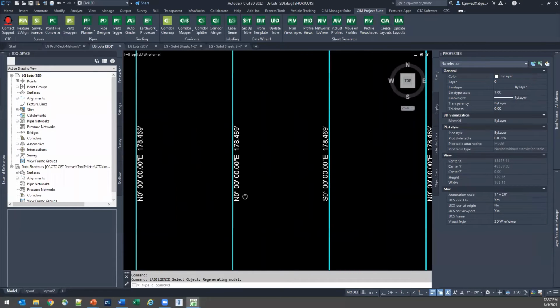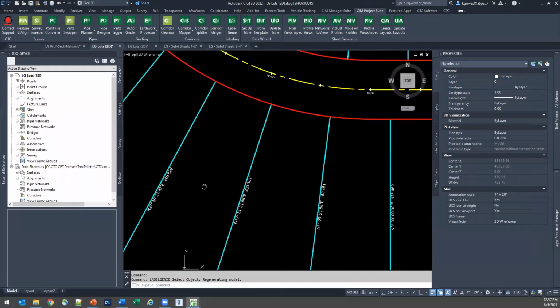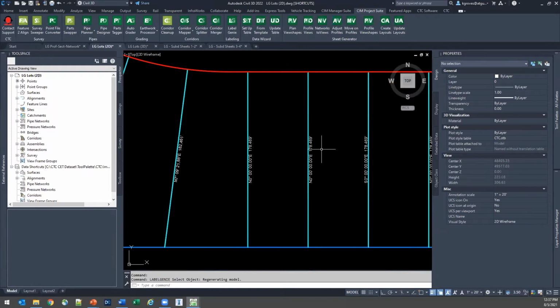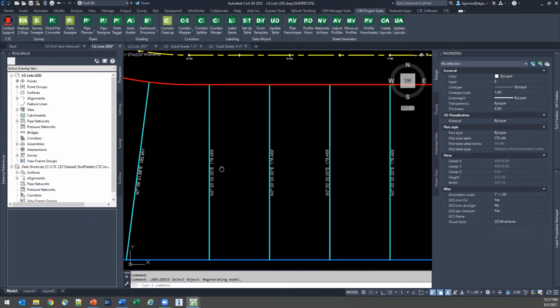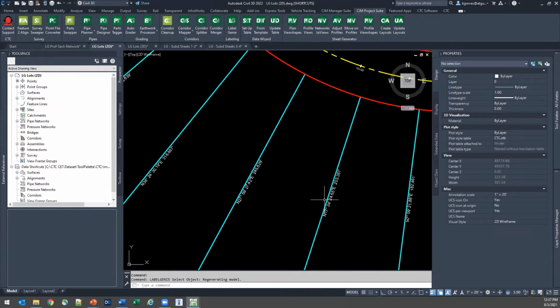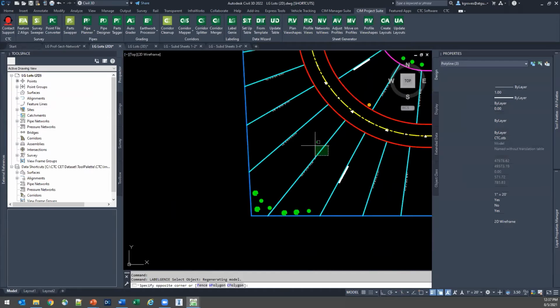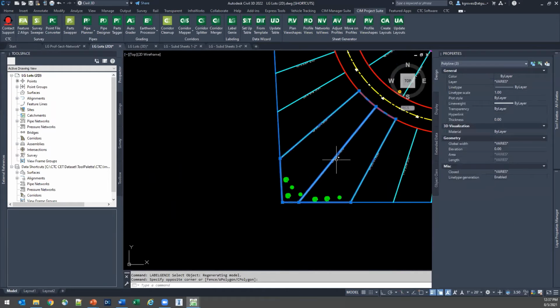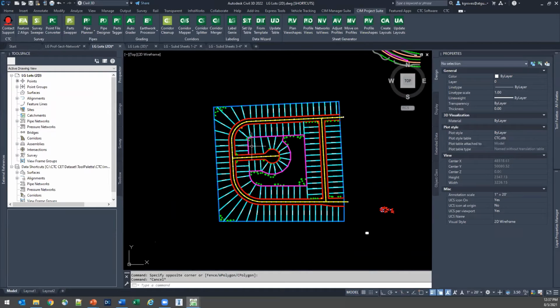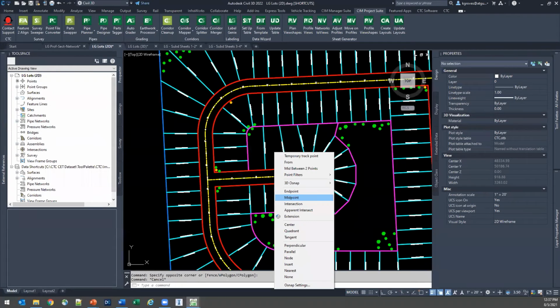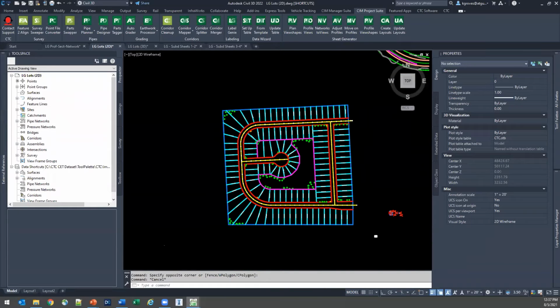Here we go, coming across our southern lot. Most of these are due north and uniformly sized at about 178 feet long. And as we continue to move through, they all got automatically inserted at the midpoint of that line. Going through and putting that in manually would be a major chore. I wouldn't have them consistent. I'd have to constantly be doing my temporary snap menu or typing out my little mid snap to make sure that they went in correctly. It's going to take me a long time just to get these side lot labels in.